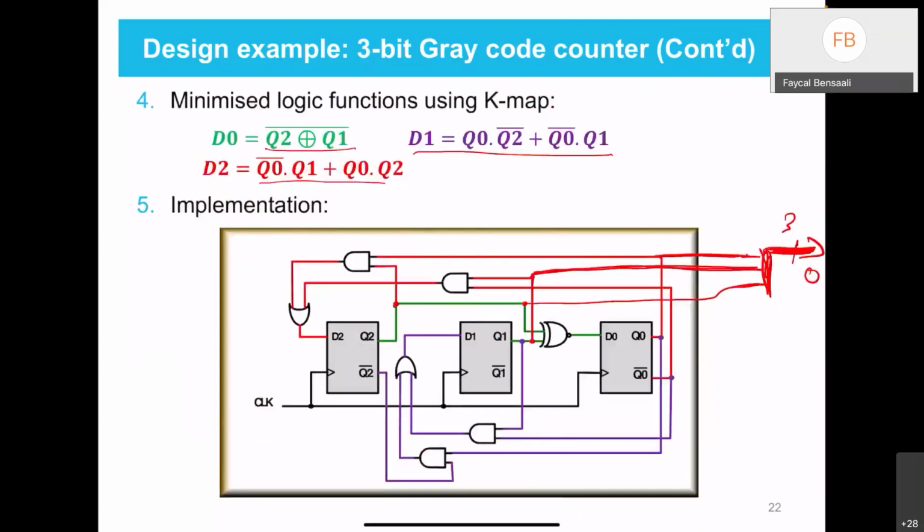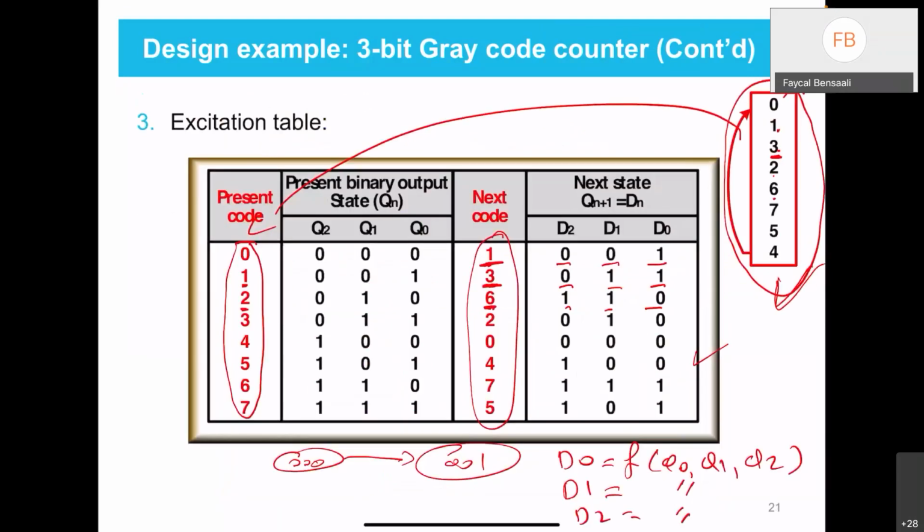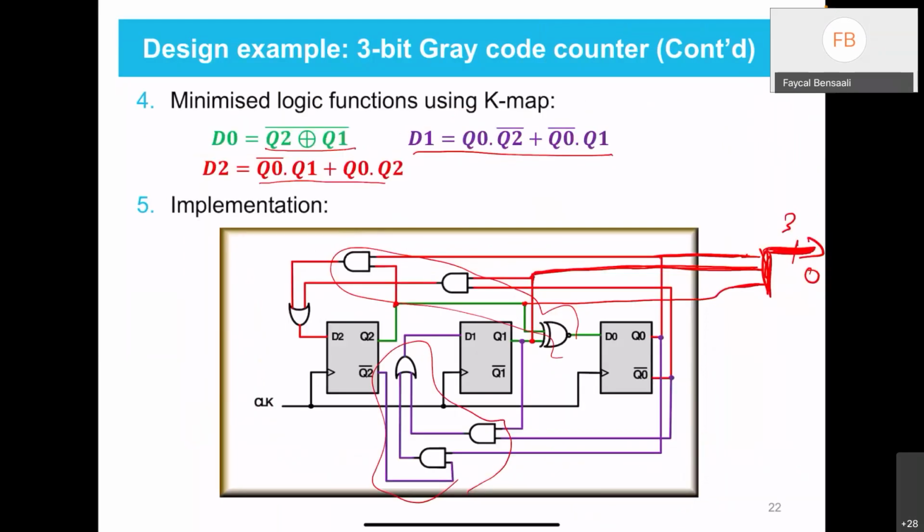So basically you can do whatever sequence you want. Of course, the circuit can get complicated. I think one simple solution is to use multiplexers. This is easily done if you use a 2-level MUX, and this will simplify your circuit further.